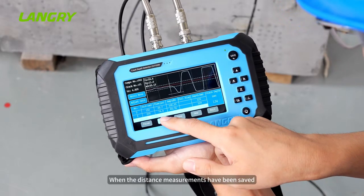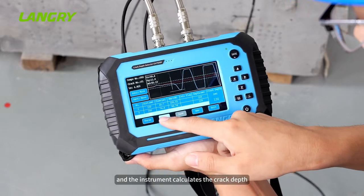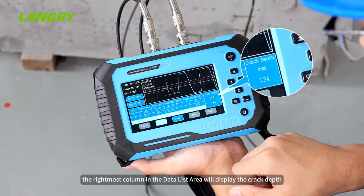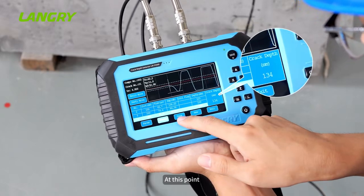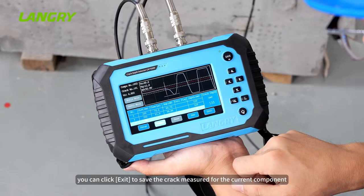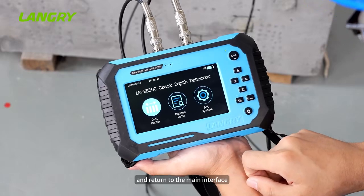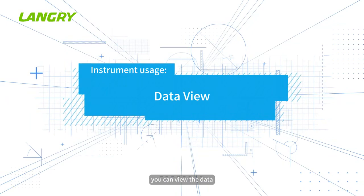When the distance measurements have been saved, and the instrument calculates the crack depth, the rightmost column in the data list area will display the crack depth, which is the final result of the crack test. At this point, you can click Exit to save the crack measured for the current component, and return to the main interface. After completing the crack depth test, you can view the data.